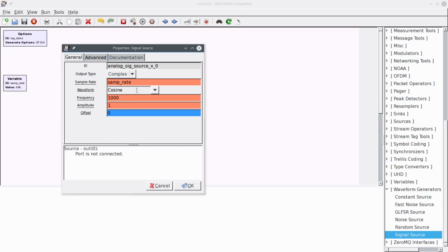So in this particular case, we've got a cosine waveform. I think I'd prefer a sine, but it doesn't really matter. And you see you've got other options like squares, triangles, sawtooth. And you'll notice that's really a number. So if you look in here, let the mouse float, it'll say that the sine is 101, but like the cosine was 102, and the square wave is 103. So those names are just handy, but the numbers are what's really important, and remember that because we're going to take advantage of that later.